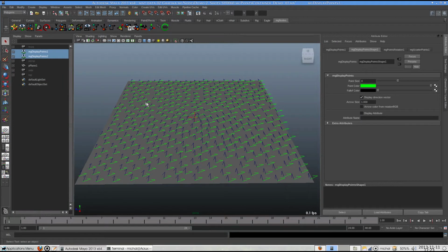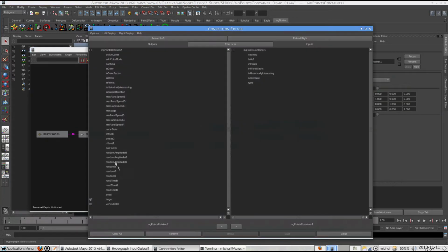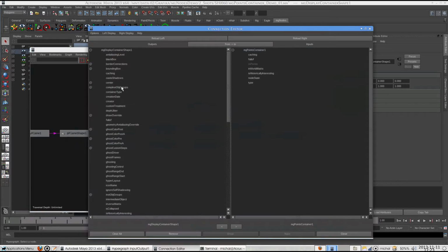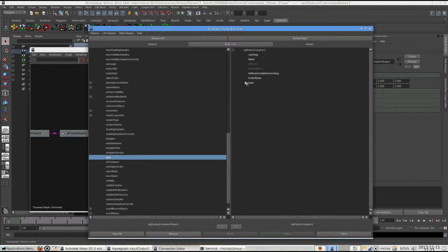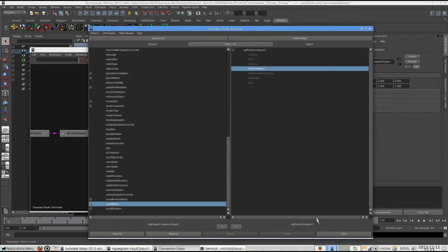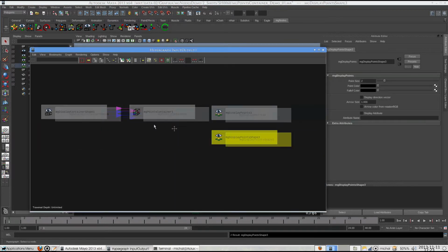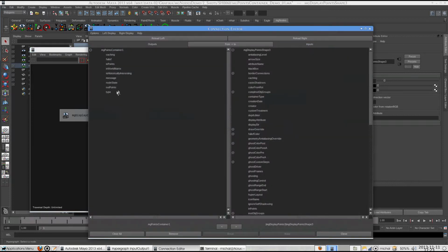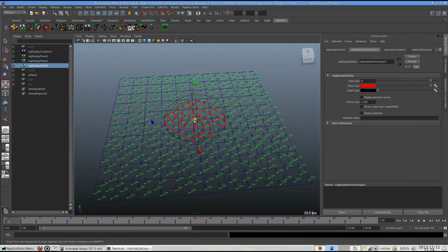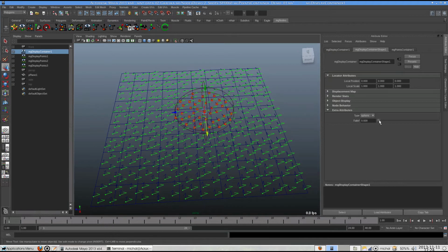It is possible to select points based on an object present in 3D space. This feature is useful in cases when we want to blend point attribute values depending on position of an object in world space. In this example, aim direction attribute is blended between two sets of values presented in viewport as green and blue arrows.